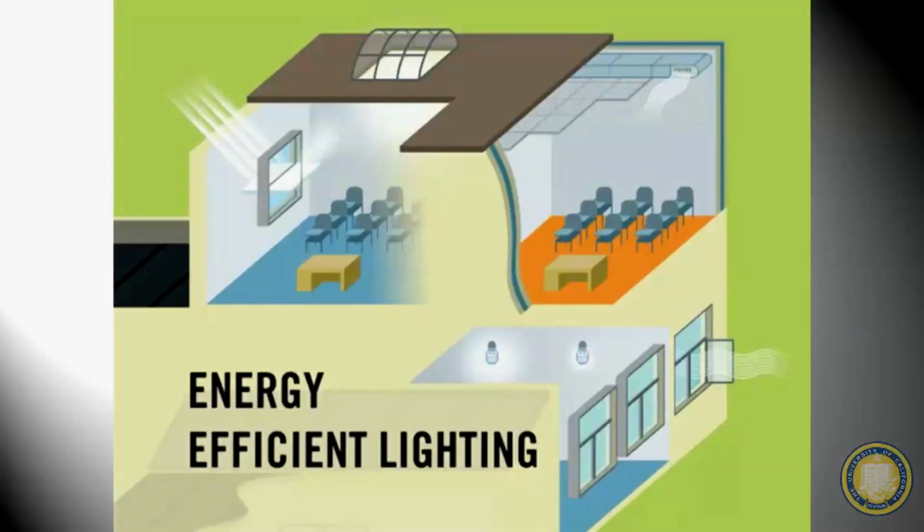Energy efficient lighting. So here we have, some people already mentioned daylighting. And this is to help reflect the light evenly throughout the room. So it's not just about energy efficiency, right? It's about the atmosphere of the room, how this environment is for the occupants of the building. And then we have LED lights here. And we also talk about how, obviously at UCI there's a lot of remote sensors. So when you walk into the building or not, the sensor goes on and off. And having individual control over your light. So task lighting, if you have a desk and it's a bunch of offices, why do you need a lot of overhead lighting? If you have task lighting and then remote sensors, that can reduce energy use and also make the occupants feel like they have control over it.